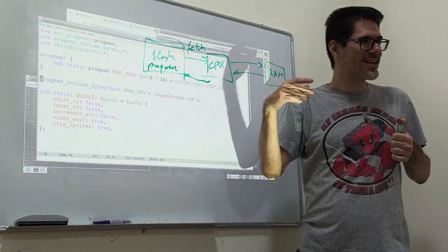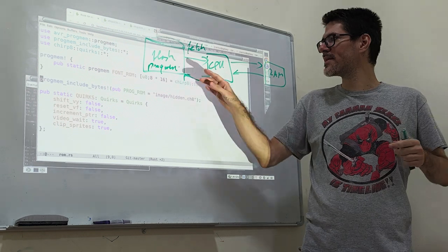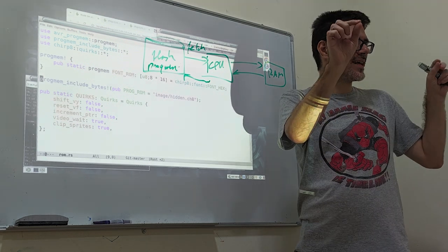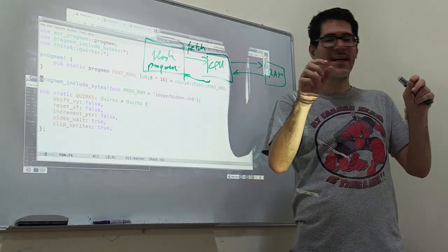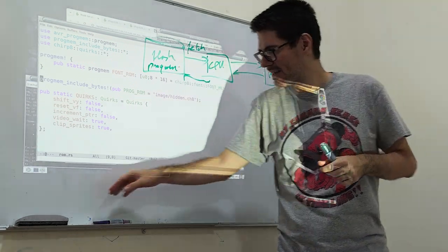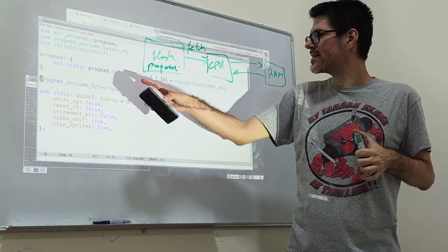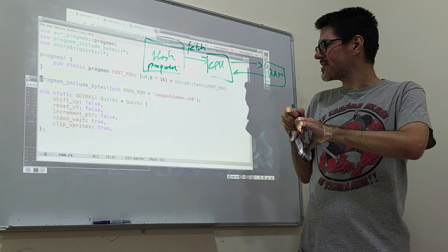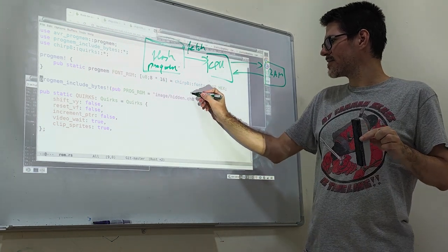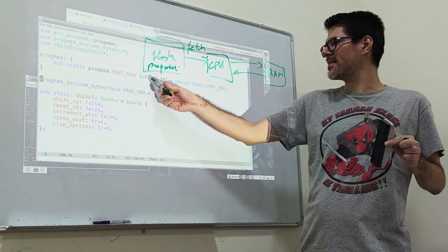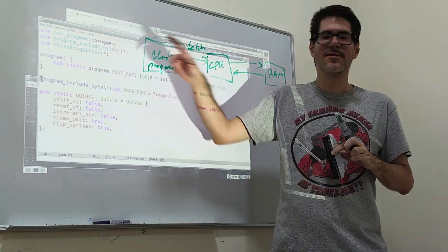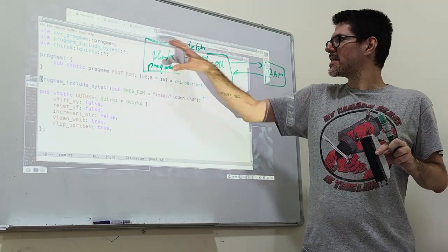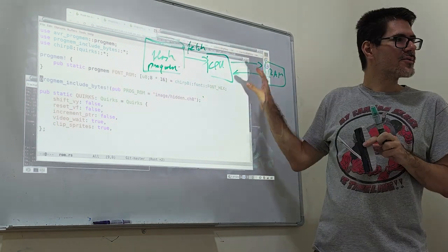Because in reality there are ways of doing that, but it's super clunky. It's not going to be byte based, but you might be able to take a 1K window that you can then overwrite completely. It's going to be very slow, right? But this is not really suited for storing runtime data there. So what this AVR program library does is it allows you to say in your program, okay, I have this static array of bytes, and you mark it as program, and that means it's going to be part of the thing you upload into flash, but it's not going to be fetched at the beginning and put into RAM.